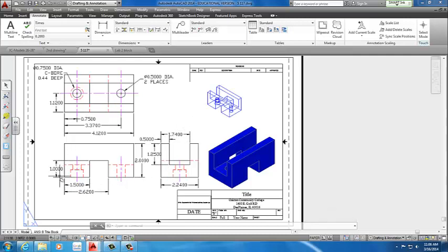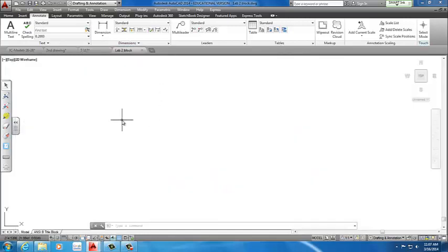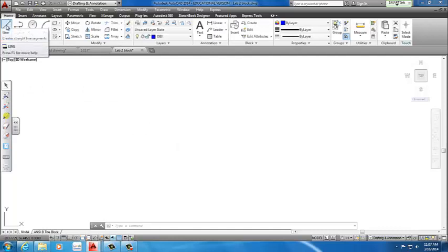Basically, we're gonna use line commands and basically create what we want to do, these parts. We're gonna create a circle. But before we do that, I want to make sure that I create that title block, and we're gonna start our drawing at 0, 0. So we go home to start with our line commands. To do that, sometimes the easiest way would be to go to line command and we start at 0, 0. So type in line 0, 0.